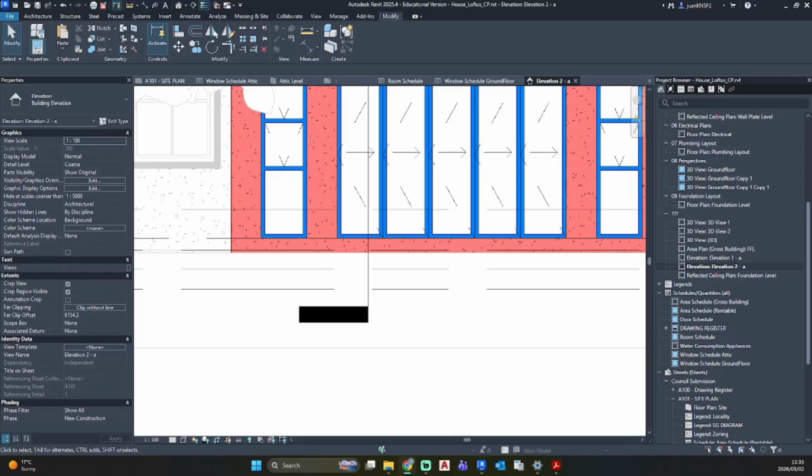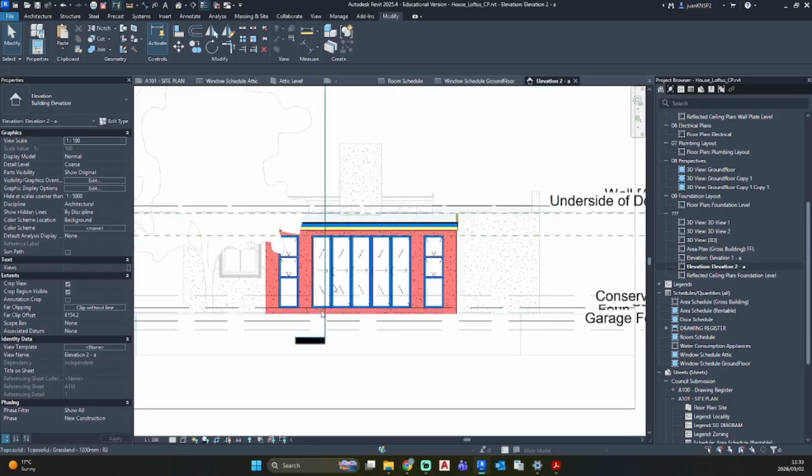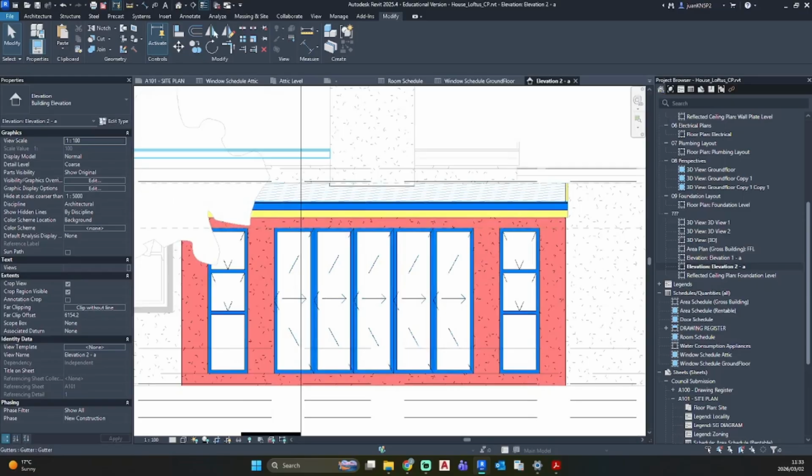We'll need light roofs, profile sheeting, yes. And we then need, what do we need? What do we need? 4 to 5 brick courses. Minimum number of courses above pre-stressed lintel. We have 3 meters. So we need 5 brick courses.